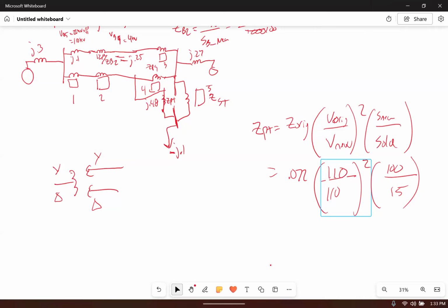Okay. Because again, unless it's a buried tertiary, then perhaps you'd have that fictitious bus, right? Because with the buried tertiary, there is no external winding. So then you would put a fictitious bus for that. But if it's not buried, you actually have a winding that you can access physically. And so that would be a separate bus location, an actual separate one.